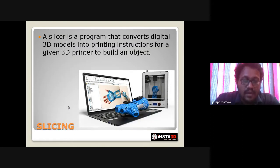So let's come to slicing. Once a 3D model is generated from a design software, we convert it into a common file called an STL file. It's called Standard Tessellation Language, STL. You can see this file format in every 3D design software. Like if you are using SolidWorks, just after designing your component, you will save it in STL format. It is a mesh-like file, and the 3D printing software accepts only STL, OBJ, or VRML files. So these are the general categories which are inputted into the slicing software.